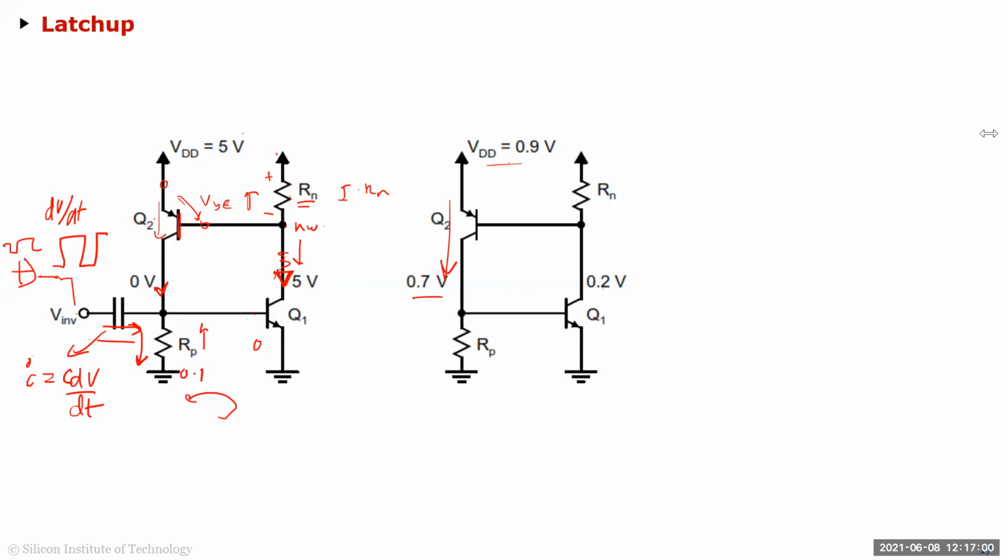Okay, so what is creating this whole positive feedback loop? Obviously having the two transistors, right? So you can say, oh, just remove the two transistors, but that's part of the PNP structure. If I remove the transistor, I have to remove the MOSes. That's no good, right? So you can say, oh, reduce the beta, right? Just make the current gain less than 1. If your beta is less than 1, then you won't have this increasing current. The current will just keep decreasing and they'll never latch up.